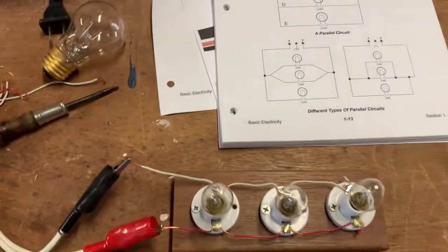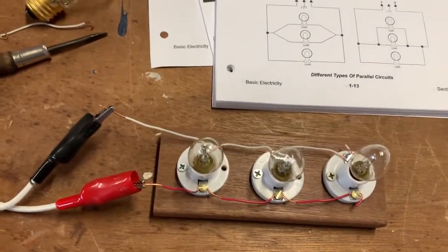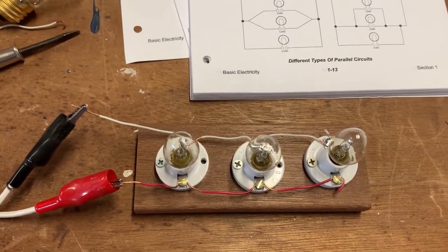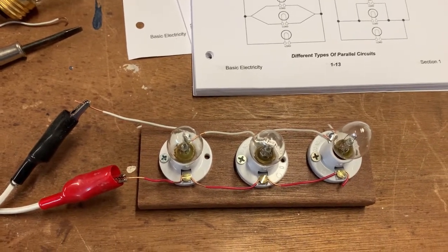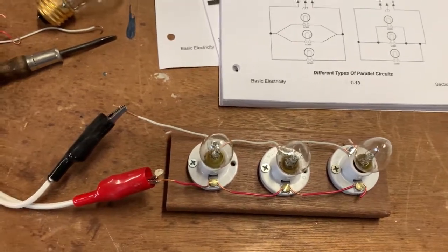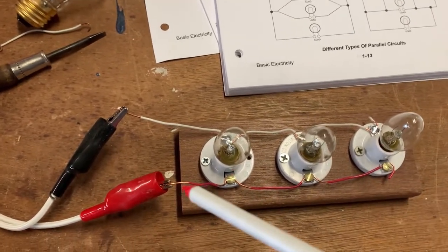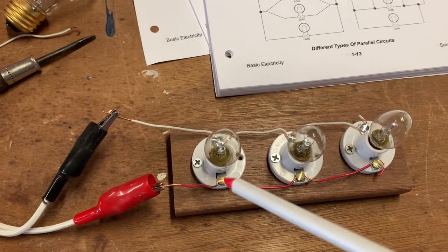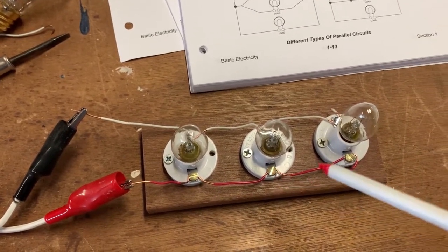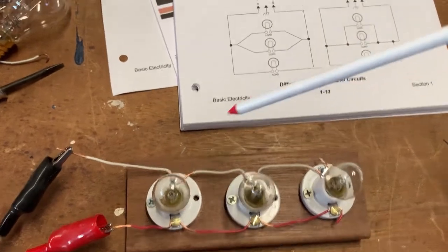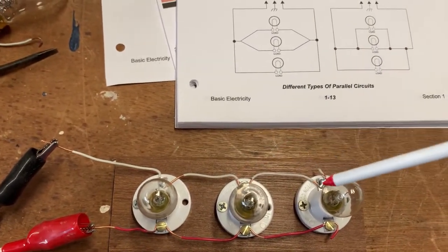So I've rewired our little test lamps here to be wired in parallel. And remember, with parallel, neutral and line are connected independently to each of the loads. The loads in this case are little lamps. So line is connected here, line connected here, line is connected here. Neutral is also connected to each lamp